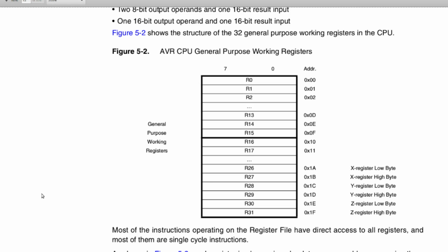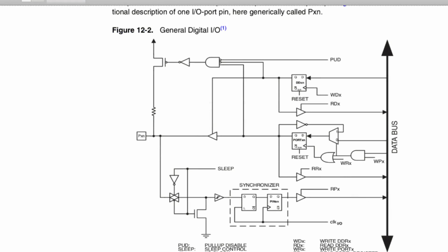From our perspective, the more important registers are the input-output registers. When set up properly, bits set in an output register appear at the physical pins of the microcontroller as highs or lows. And highs or lows placed on the physical pins of the microcontroller appear as set or unset bits in the input registers. This is how your input and output is communicated outside of the imaginary world inside the microprocessor.